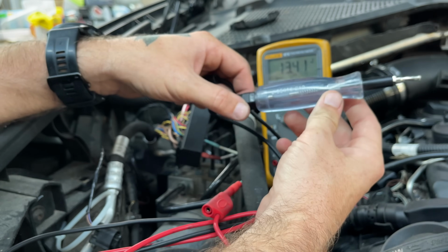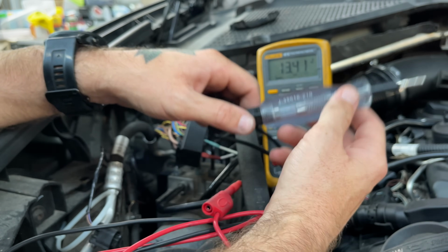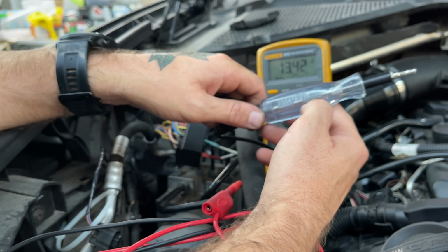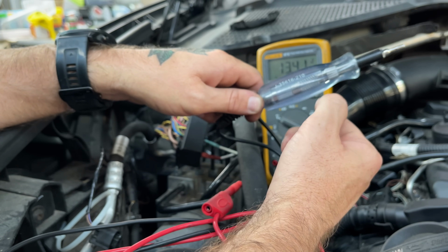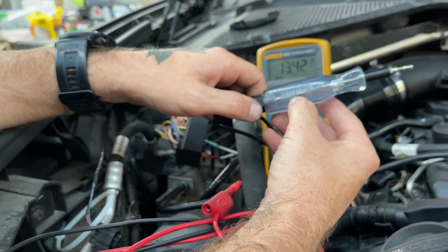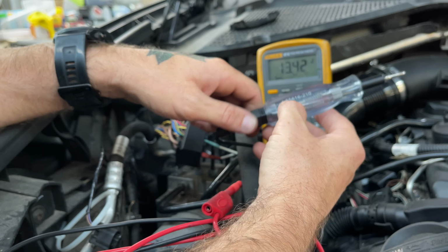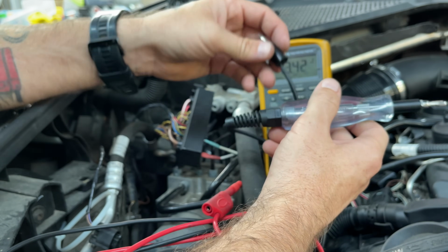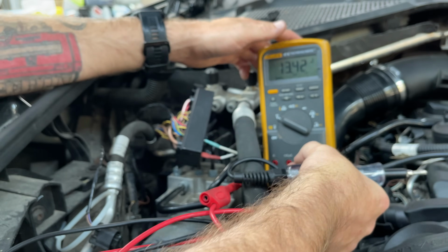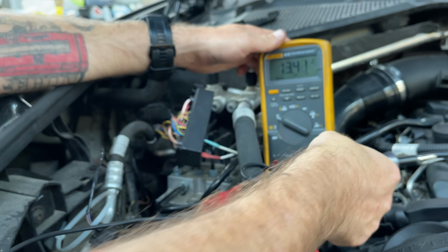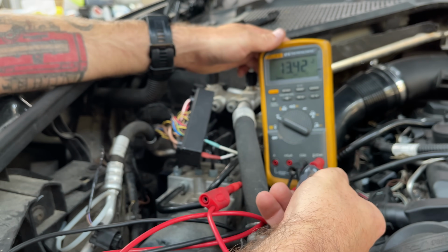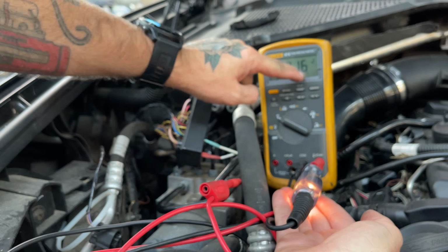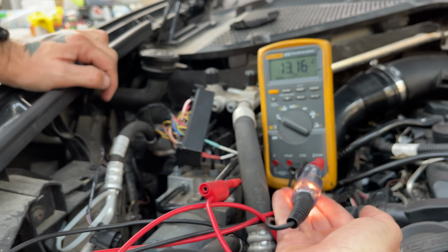It is module safe, computer safe. It takes roughly 50 milliamps to light this bulb at 12 volts. This thing is voltage dependent on how much current it takes. So at 12 volts is about 50 milliamps. So let's see what happens with it. Look at that. Bulb is on. We have 13 volts still.